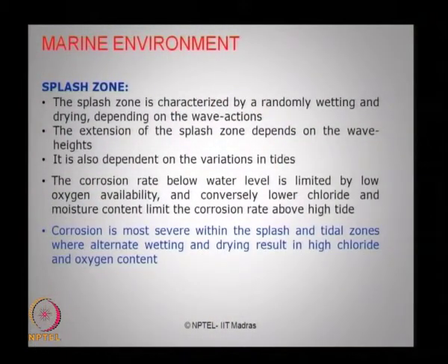The splash zone is characterized by a random wetting and drying process. It of course depends on the cyclic action of the waves. The extension of the splash zone depends on the wave height at a specific sea state. It depends on the wave height at which the operational design has been done for the platform. It is also dependent on variation of tides in a specific sea state.